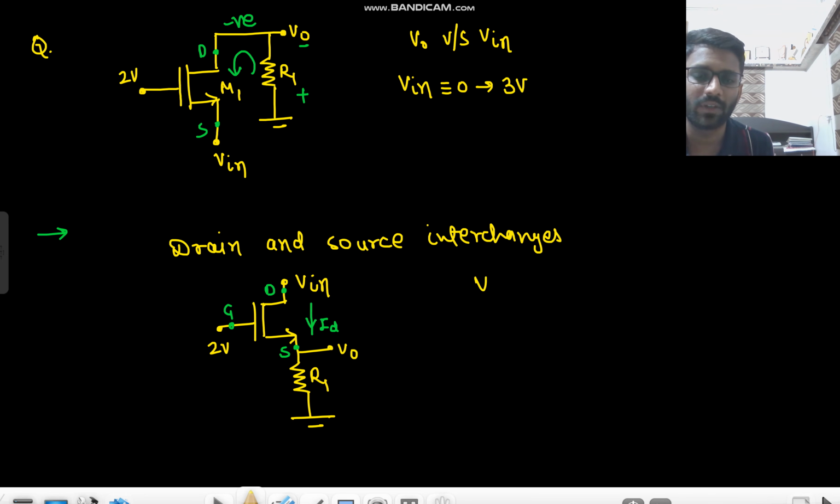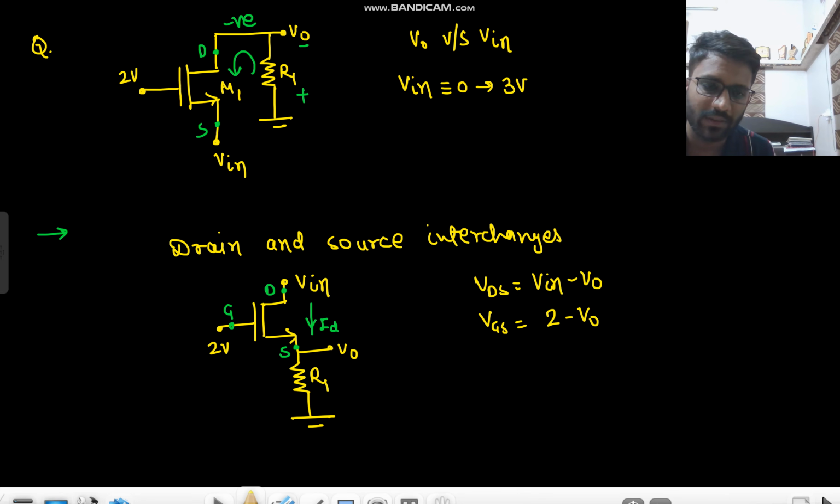What is VDS? Vin minus Vo. What is VGS? 2 minus Vo. What is V overdrive? 1.3 minus Vo. This is the condition.